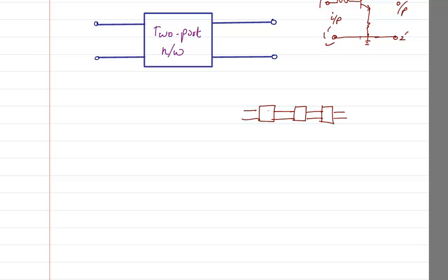You have the first part of the circuit which is a filter, the second part which is basically an amplifier, and the third is, let's say, a power amplifier. So this three-stage circuit, you can analyze by doing an analysis of the filter, an amplifier, and the power amplifier separately, and then join each of them together with the help of the ports.